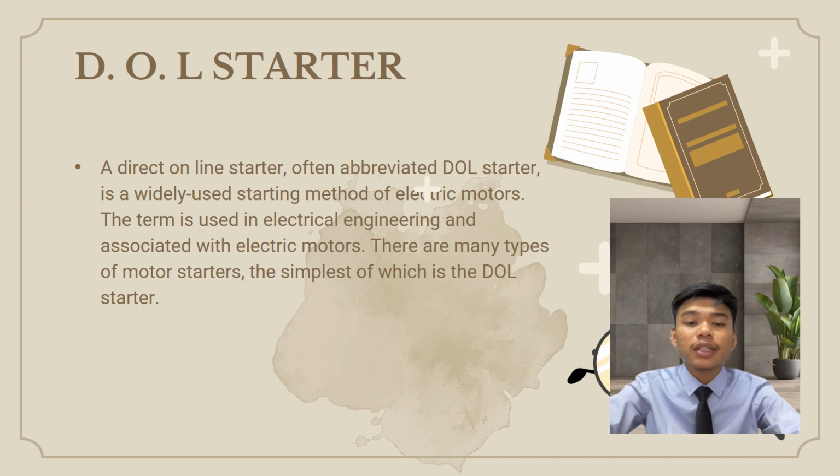A DOL starter connects the motor terminals directly to the power supply. Hence, the motor is subjected to the full voltage of the power supply. Consequently, high starting currents flow through the motor.